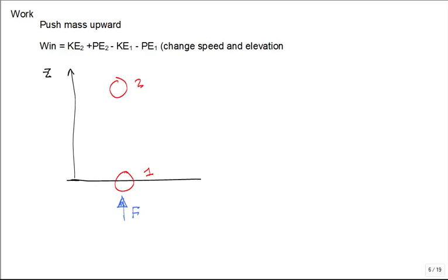But one of the things that you have to worry about is, guess what's always acting on that mass? In the gravitational field, g, the force known as the weight, the gravitational weight. True? Oh boy, I don't like this problem, right? But I want to now get an equation where I have that work, the integral F dz, not dx, but dz now, because I'm going F in the direction of dz, changes the kinetic and potential energy from the beginning to the ending state, right?